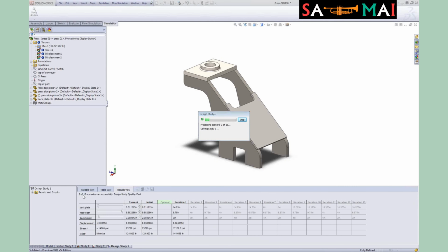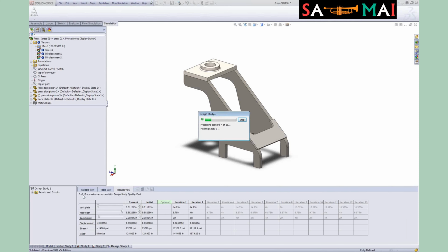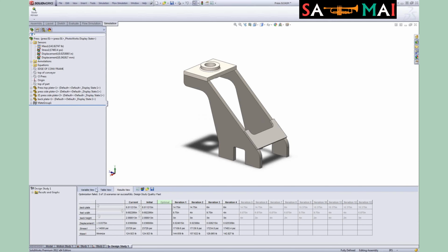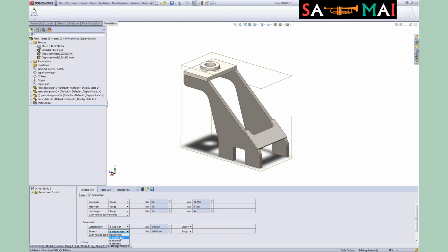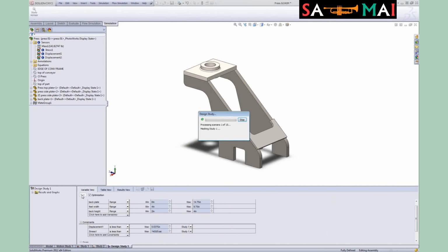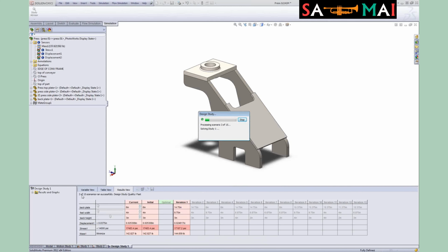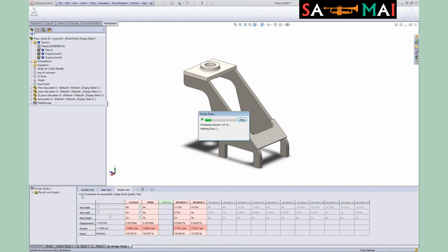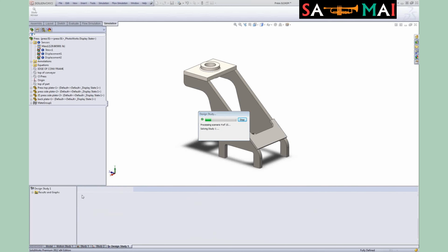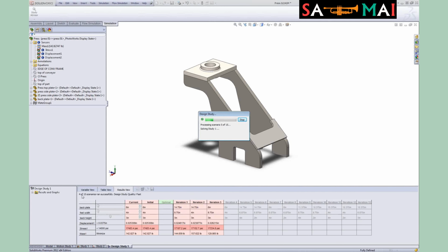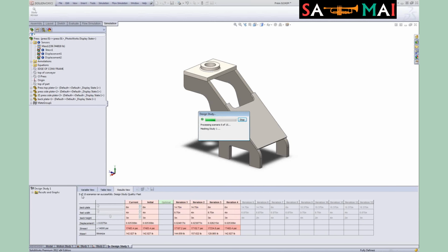So as we allow this to run, we should see several others that are actually going to fail here. And we want it to be less than 14,000. I apologize. So let's rerun here. We should receive good results. There we go. Anything that comes up in the red or pink color is actually failing, and it's failing due to the fact that the stress is too high.